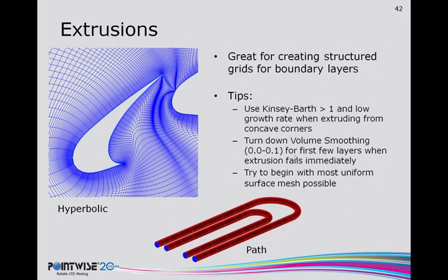Another extrusion tool I'll talk about are the path extrusions, and here you can generate a single topology at the outlet and then extrude that along a connector to rapidly generate three-dimensional blocks from that. So here, these are just a couple of tubes from, say, a heat exchanger or something like that. The only downside to this is that the path extrusion requires a constant cross-section. So if your cross-section changes along the path you're extruding along, then the path extrusion isn't going to work, unfortunately, and you'll need to generate that topology by hand.